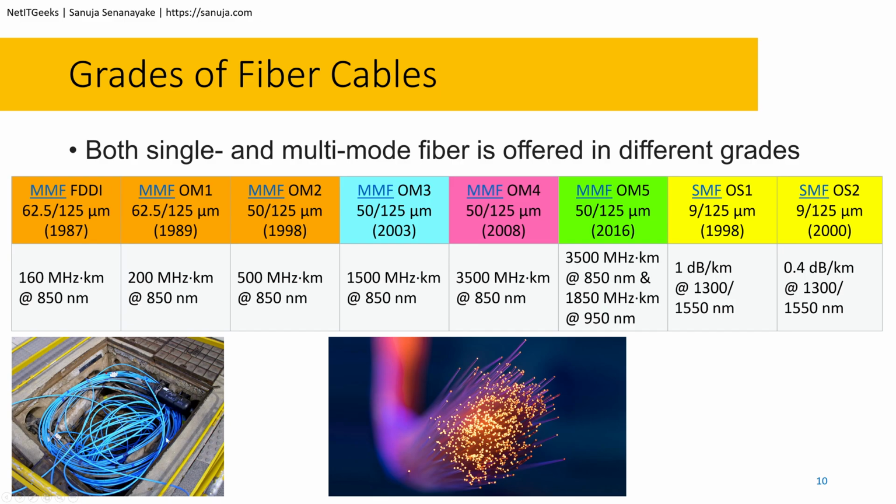And here is a picture of a fiber optic communication cable in an actual installation setting. This is a real cable, and what it looks like when you have communication going through. But keep in mind, not all light is visible, and not all visible light is used for fiber optics communication. That's why there are some safety concerns that you should take into account when you're working with cables that you believe are turned off. You should never look directly into these, for example. I will go over that in the next few slides as well.